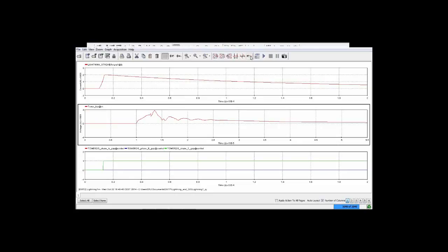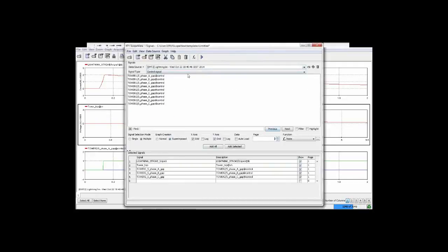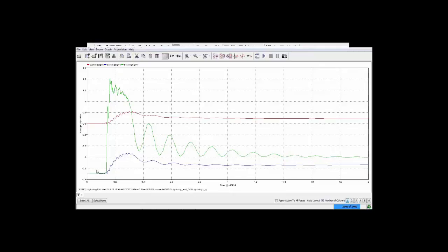So what is the impact of this flashover? If I look at the voltage at the bushing at the entrance of the substation, I actually see that the voltage C, after it flashes over, goes slowly to 0. This is because one of the insulators tripped, and here we lost the phase.